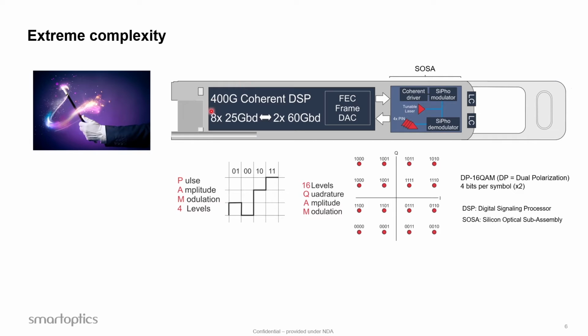This is then going into your DSP, or digital signal processor, that's doing some magic around this, and then you take it through your silicon photonics optical subassembly transmitter block, where you add a coherent signal and so on. And then you go out on a standard LC duplex connector, with one transmit LC and one receive LC connector. The line side will have a 16QAM modulation. So it's amazing that all of this fits into this small form factor.